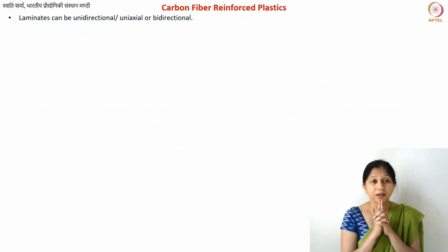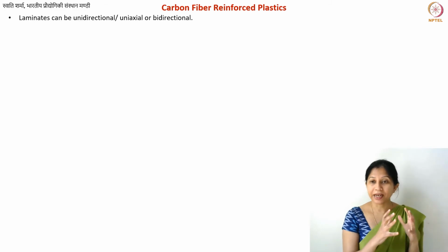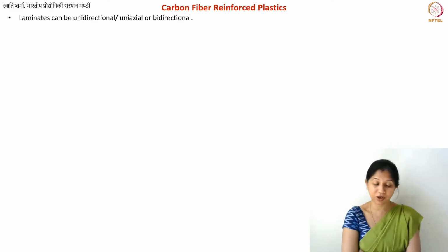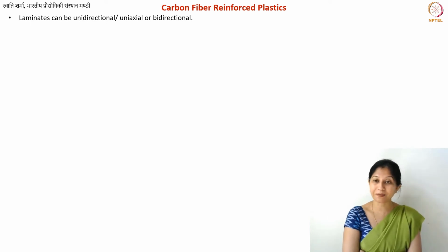Okay. Now let's talk about the laminate type of structure, the second type. So short fiber composite, you know, it will give you an isotropic material. What is very important when you are preparing any composite material, especially with carbon, is that your carbon fibers or carbon structures generally have a very high surface energy. What does that mean? That means that it's really difficult to mix them with anything.